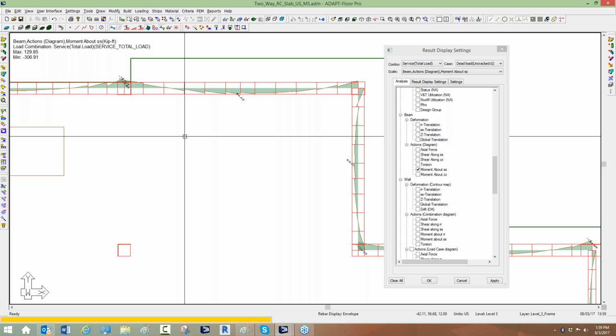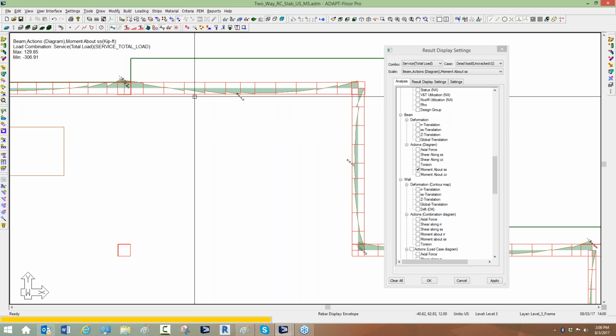but the slab also has moments at each of the shells. So once we generate the design sections and analyze them, then we get a secondary result, which is called the design section results. And the design section moment is essentially the composite moment that we calculate relative to both the slab and the beam being one combined monolithic piece of concrete.